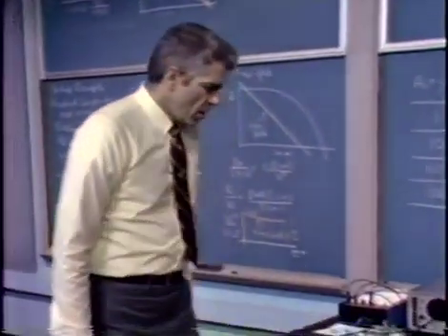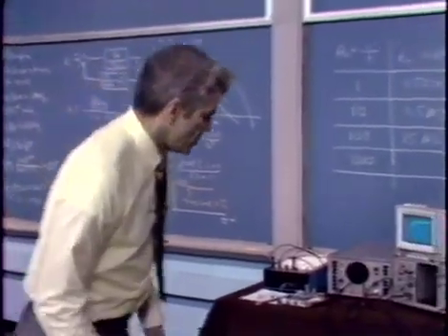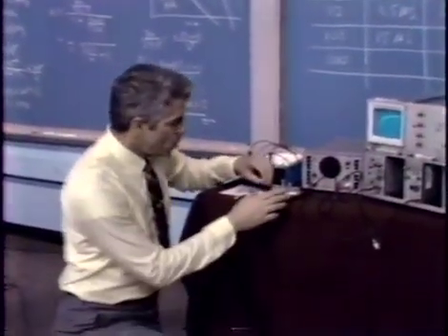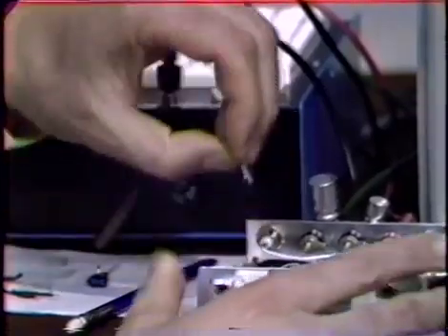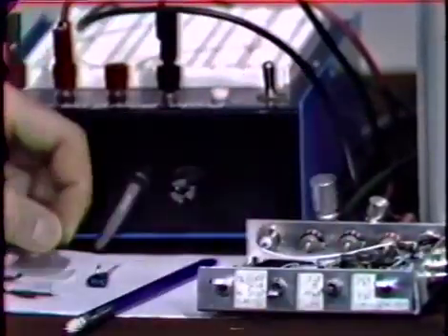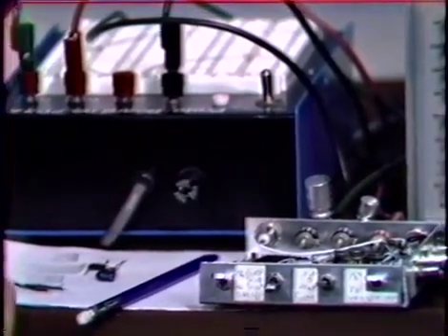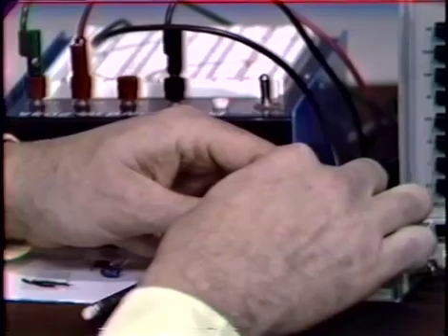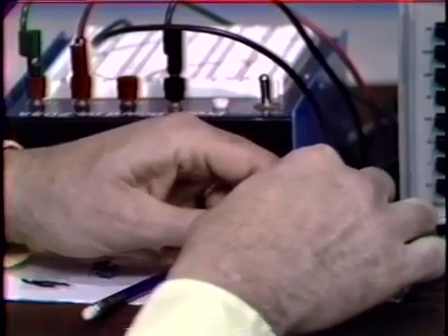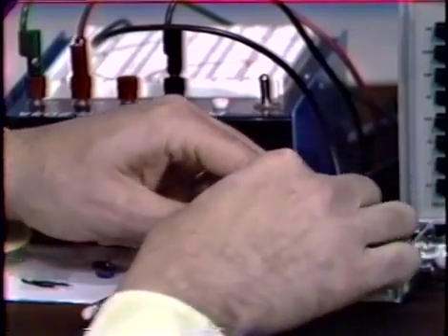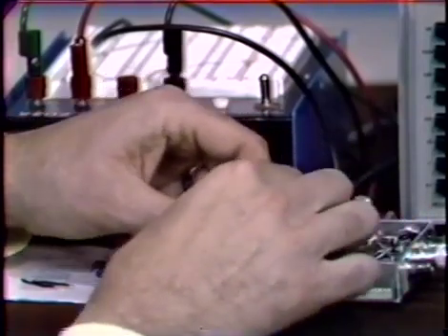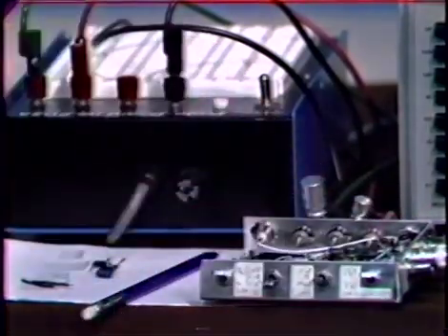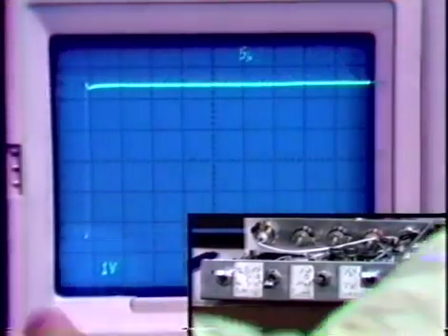Again, we can get close to our original speed of response by removing the 20 picofarad capacitor and replacing it with one that has been chosen. As I say, it's not quite 1/100th of the original value, but one that's been chosen to yield very close to the original dynamics. And we get that sort of a response, much faster.